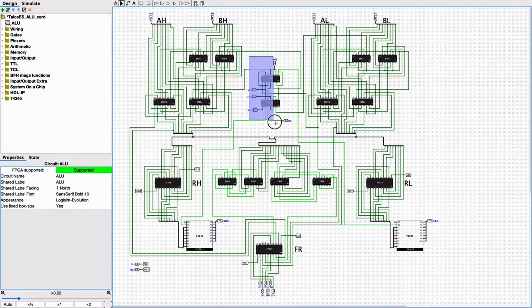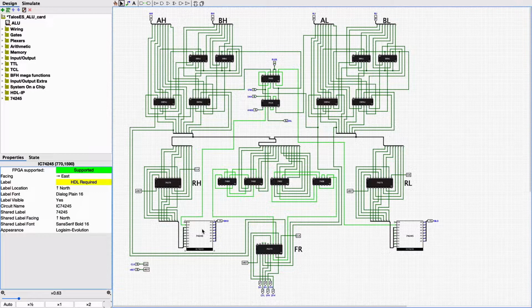And these are the two chips that form the control logic. And that's why we have two extra control inputs. That's the result high output enable and the result low output enable. And depending on whether these signals are active or inactive, these drivers will assert the corresponding value on the internal bus, or not, or they will just tri-state.